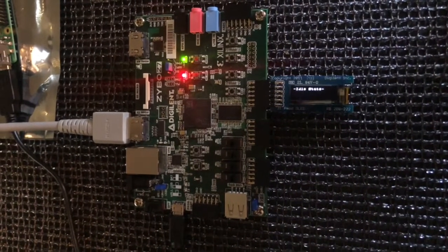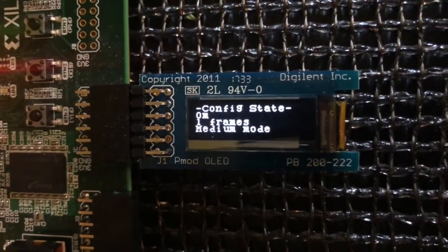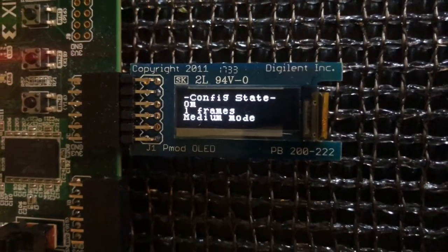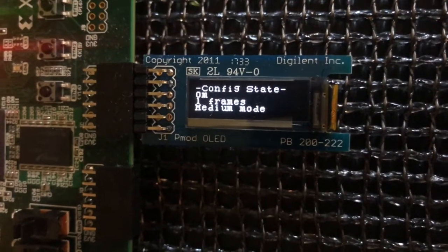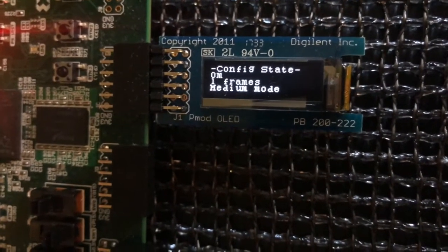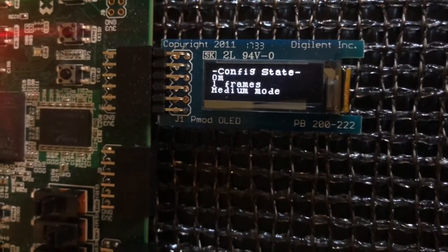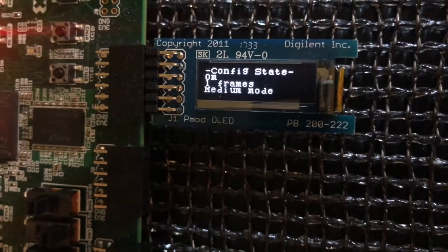Before initiating the system, the user may also configure it by toggling the rightmost switch. Here, the user has some options for setting their distance threshold detection value, the number of data frames they'd like to collect, and the detection range of the system. By default, the distance threshold value is 0, the number of data frames to collect is 1, and the detection range of the system is set to medium, which denotes a range between 1 and 4 meters.